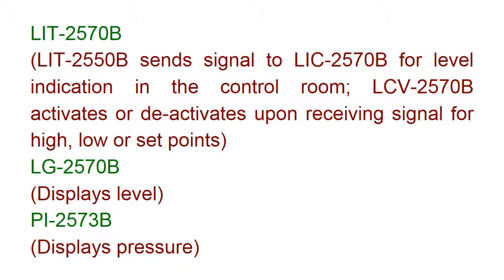LID2570B. LID2570B sends signal to LIC2570B for a level indication in the control room. LCV2570B activates upon receiving signal for high, low or set points.